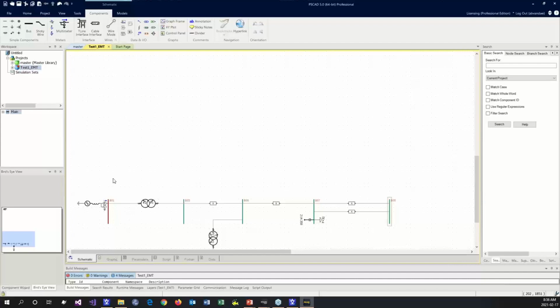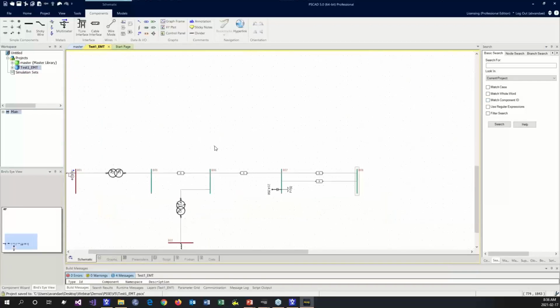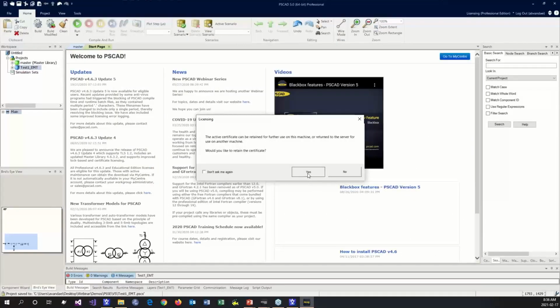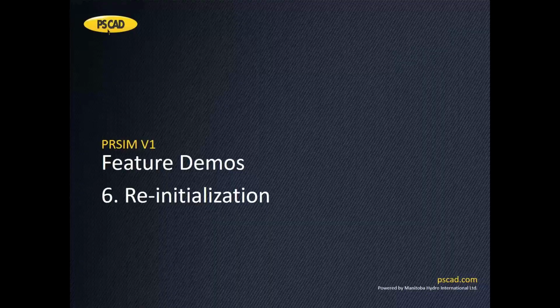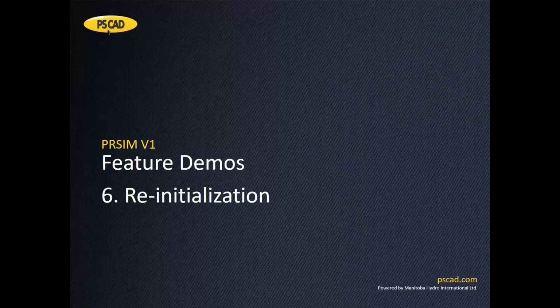For example, you may want to add multimeters, add more control parameters, and monitor a number of signals. But what you want to do after this is, for example, further expand this bus bar, which is a boundary bus, and look into more details of the case. And obviously, you don't want to do the whole process of importing the information again, because that's not a big change. That's just updating the existing PSCAD file.